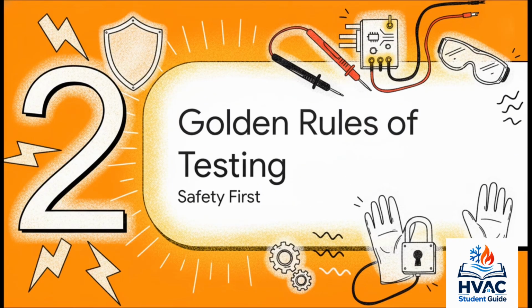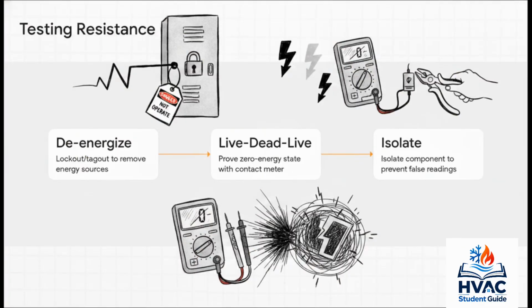It's more like a toll booth, making those electrons do some actual work. Moving right along to Section 2, the golden rules of testing. Okay, this is your absolutely mandatory isolation sequence when testing for resistance. Step 1, de-energize the circuit using proper lockout-tagout procedures. Step 2, perform a live-dead-live voltage test to definitively prove it's dead. And Step 3, isolate the component.